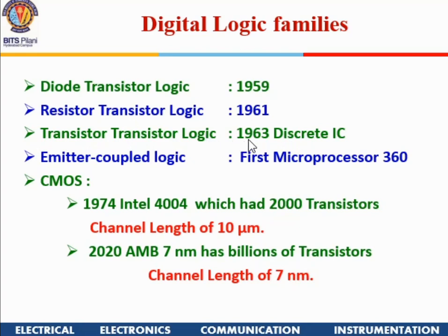Even today it is used. Even in our lab, we are going to use TTL logic circuits. They are discrete ICs. The TTL logic is not used in microprocessors or VLSI chips. You will have a TTL NAND gate, TTL NOR gate, TTL flip flops, TTL counters, TTL adders, but you will not have a TTL microprocessor.